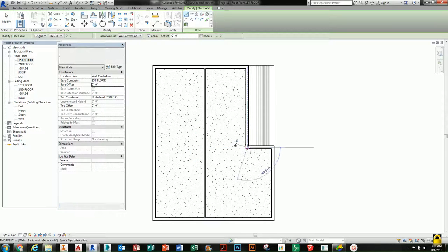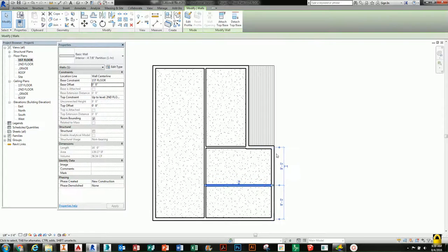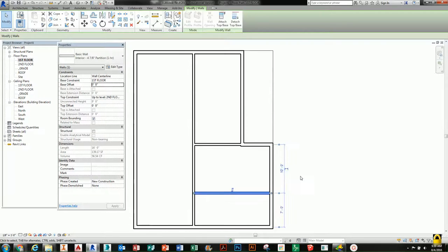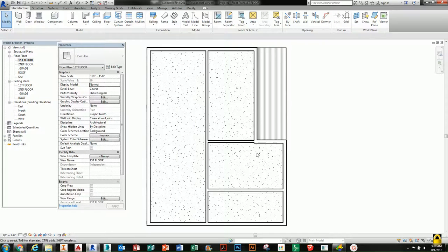We have one that goes here. We also have one here. And this wall should be 10 feet from the inside. So we'll go 10. We have a basic outline. You can use the AL command to align faces of walls to make nice clean connections.